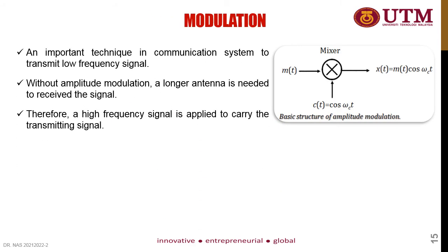Okay, the next application that will be discussed in this chapter is the modulation process. This is one of the important techniques in communication systems to transmit low frequency signals. Why do we need modulation? Because low frequency signals are easily affected by noise.